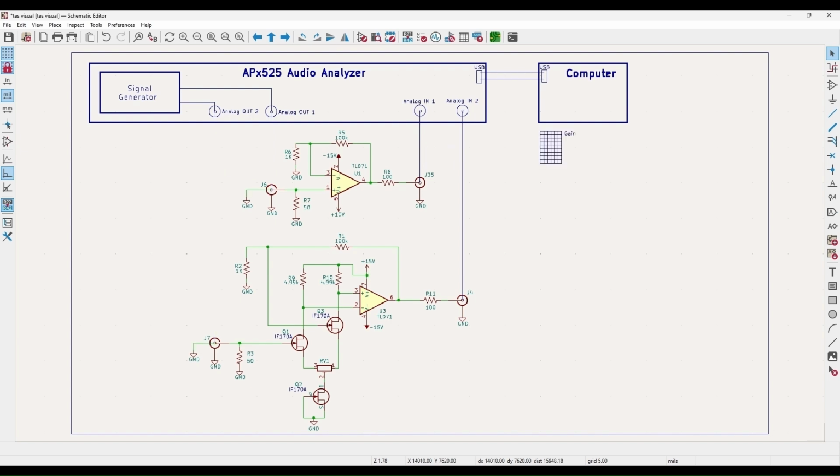The sine wave is turned off and the inputs to the modules are shorted to ground. When the analyzer samples the analog inputs, it records circuit noise and stores those values in a noise file. This results in an average of 10 samples of the audio band by the analyzer. We will repeat the noise sampling process 8 more times for a total of 9 noise files.